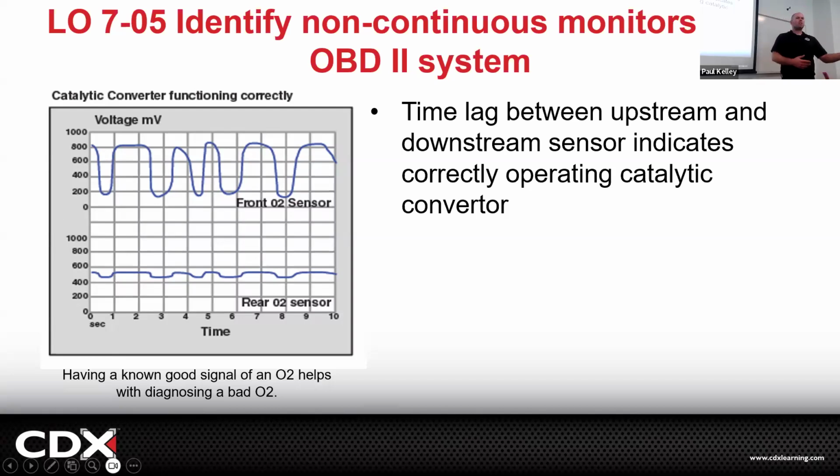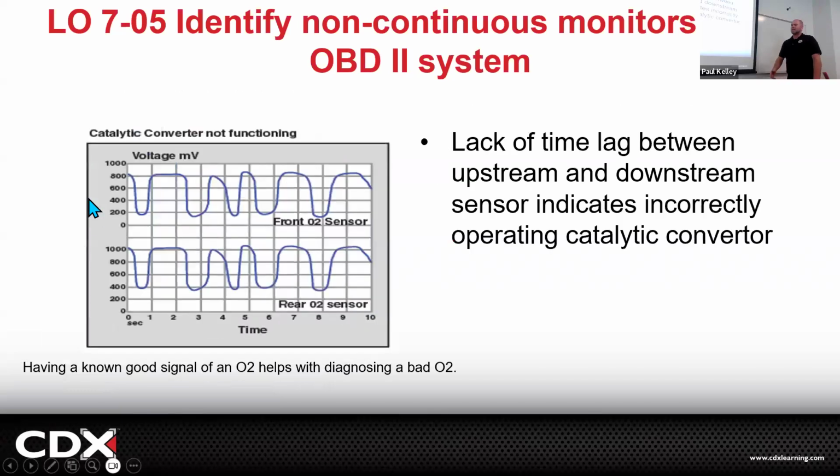Is it an exhaust leak? There's more possibilities, and you might have to do a little bit more advanced testing. Whereas if it's a circuit code, I'm right down to the voltmeter, checking voltage and figuring it out, right? Then you get into these other codes like the P0420.